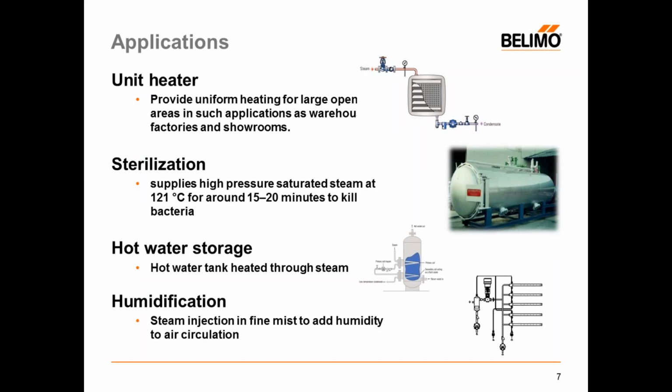Sterilization, not too common in our HVAC world. Hot water storage, yes. And then humidification, which is interesting. That's the one time that through the process you will not use a trap. You're constantly draining the condensate, but you're actually putting the steam vapor into the airflow to humidify.